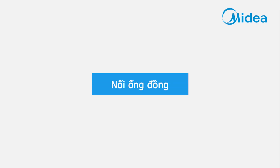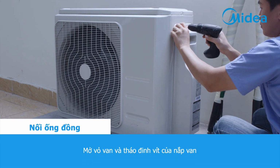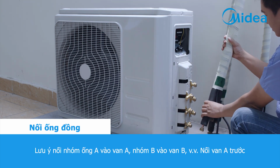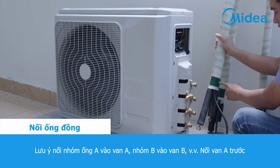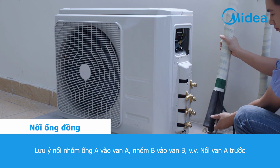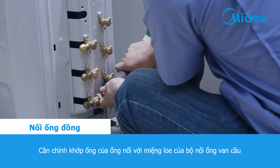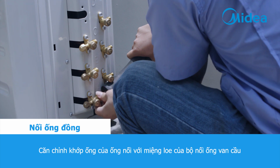Connection of copper pipes. Open the cover of valves and unscrew the valve caps. Note that connect pipe assembly A to valve A, pipe assembly B to valve B, and so on. Connect valve A first. Align pipe socket of connecting pipe with the bell of globe valve pipe adapter.